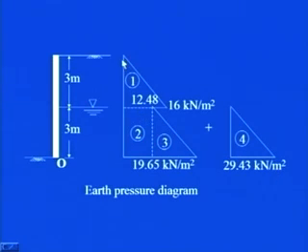So you see the area which is formed by these firm lines includes this earth pressure diagram. Now, for simplicity, because once we draw this lateral earth pressure diagram, we need to find out its area to get the total force per unit length of the wall, that is why I have divided it into 4 parts, that is 4 areas.